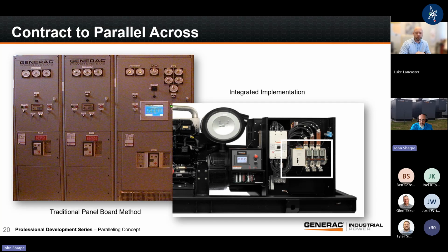This particular one that we've got here, this is what we call an integrated paralleling, something we talk about in our next class. This is a contactor. This is just a motor starting contactor switch, and serves the same purpose as the circuit breaker. It doesn't have overcurrent, but in this case, I'm not asking for overcurrent. I've got an overcurrent device sitting here. So this is just the device I'm telling it to close as quickly as I can so that I can lock these two devices together.